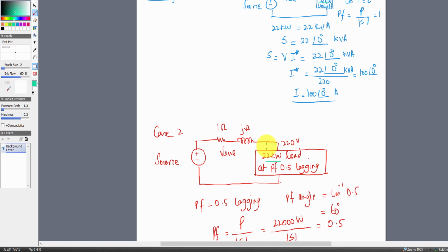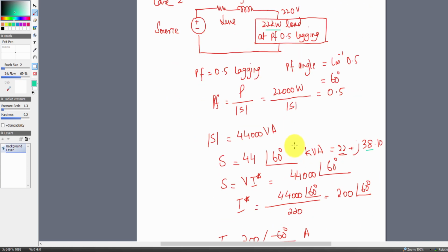If they can measure the power factor to be less than a certain value, they are going to charge you more per unit of energy, because they have to transmit a large amount of current to the load, thereby suffering large line losses on the utility side, because the consumer is only going to pay whatever is being billed at their premises. They are getting 22 kilowatts, but they are supplying a very large amount of current. That's why industrial consumers either have a power factor meter, or they could have reactive power meters, so they can figure out the power factor.